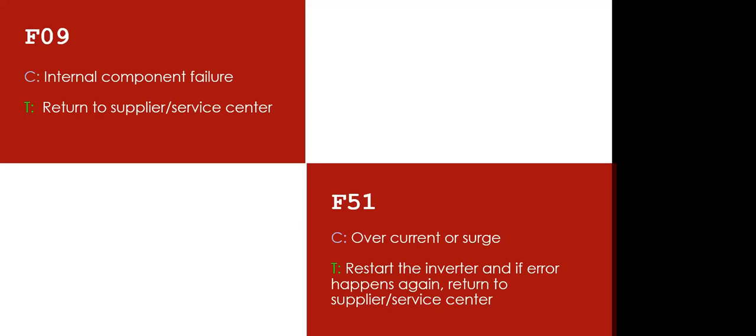And again, we recommend surge protection for the AC side and the DC side, which is the solar section. If you are using solar, we always advise to use a DC surge protector of appropriate rating. Then we also introduce the power limiter.